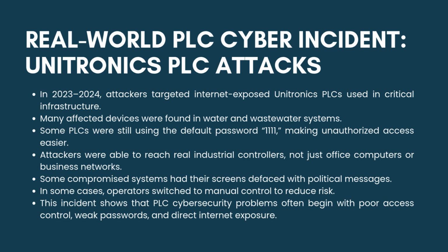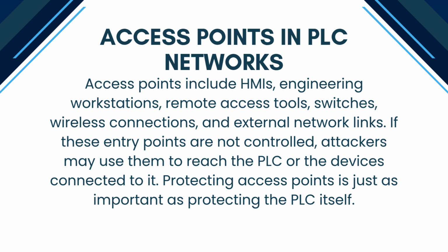One major reason this can happen is poor control of access points. Access points include HMIs, engineering workstations, remote access tools, switches, wireless connections, USB ports, and external network links. If these entry points are not controlled, attackers may use them to reach the PLC or the devices connected to it. Protecting access points is just as important as protecting the PLC itself. If the entry points are weak, the rest of the system becomes easier to reach.